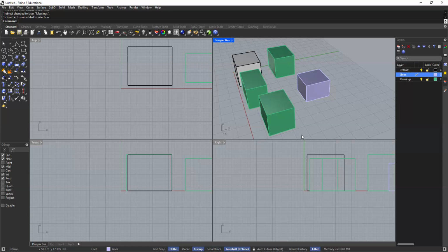And so next thing I know, my windows are in my walls layer because I never changed the setting to go into my Windows layer, right? And so then I have to go back, and you're kind of going back and having to adjust things. And then sometimes you have modeled for an entire day and forgot that everything is still in the walls layer, right? But this definitely is a preference. And you're going to begin to figure it out on your own as you model more and more. You'll find your own preferences.